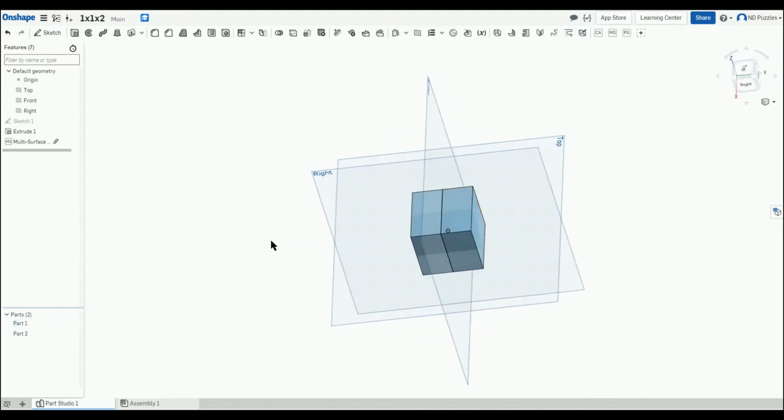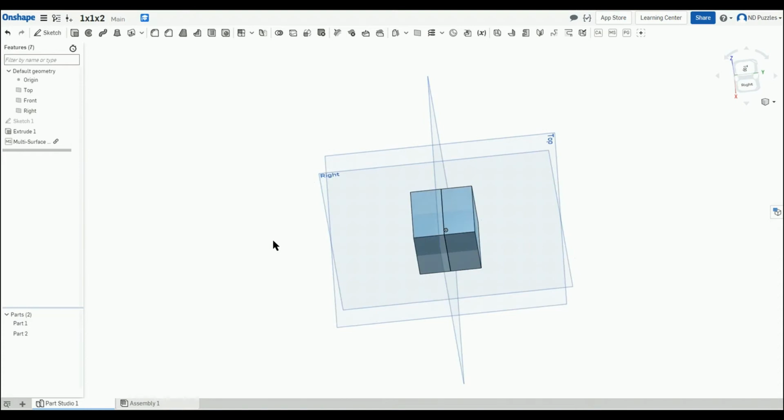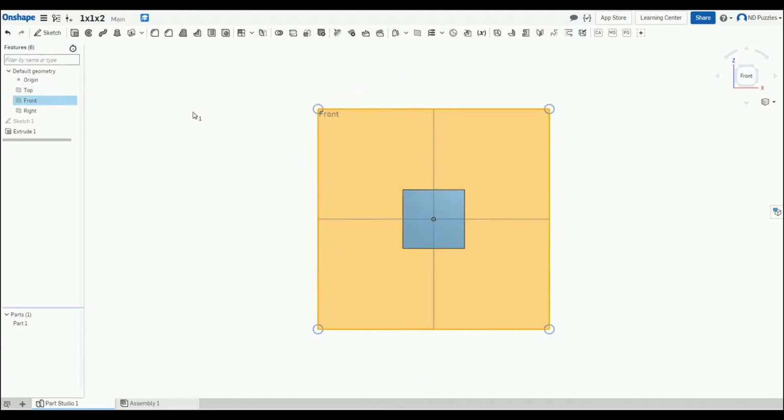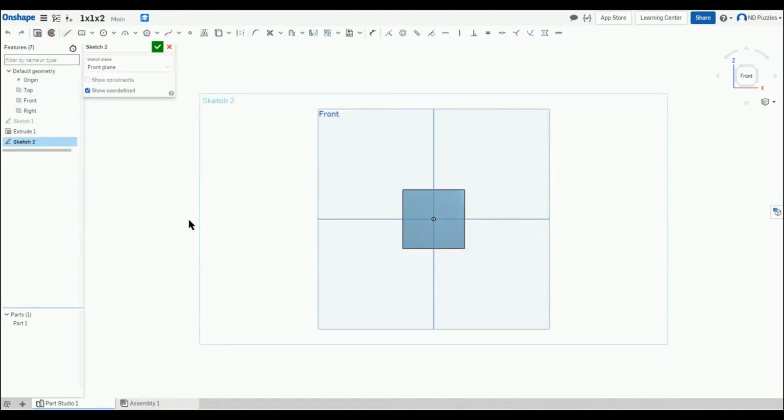To create a twisty puzzle, we now have to cut the solid we just created into pieces. If you are wondering why we use this approach instead of just designing individual pieces, that is a good point. But in puzzle design, it is common to design a cross-section of mechanisms, which makes it much easier to create pieces that actually fit into each other. It also allows you to design a puzzle without knowing in advance how every single piece will look. That might sound strange at first, but once you get this concept, it is very easy to design puzzles.